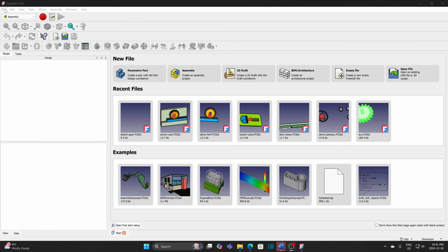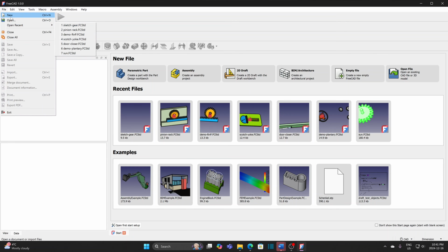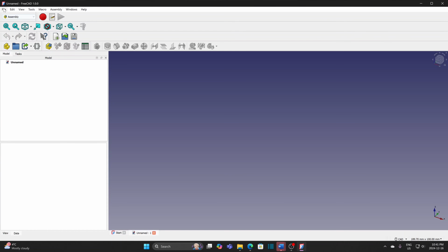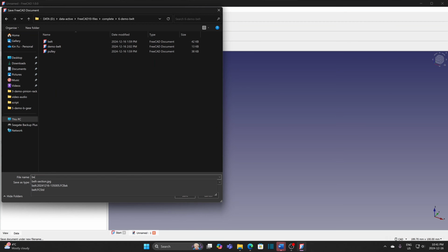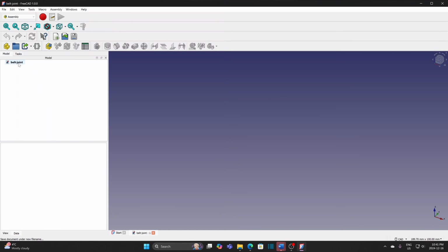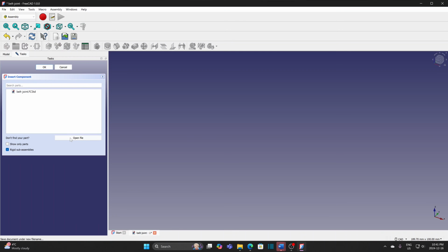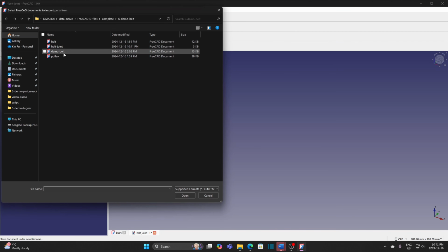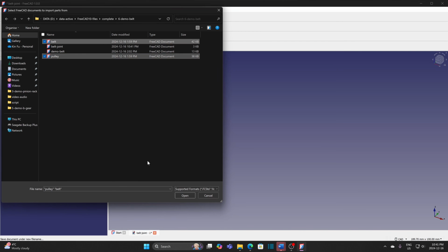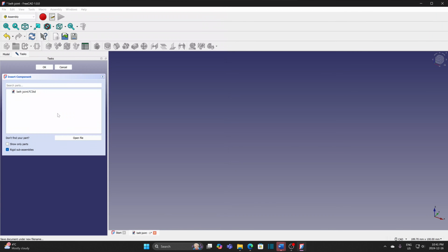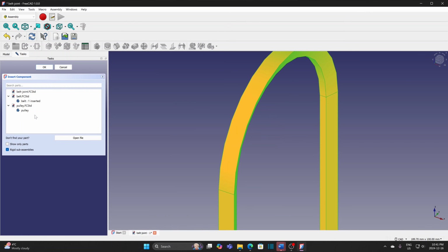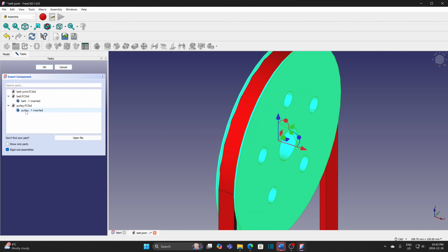Belt joint is to relate two revolute joints by the radius ratio, so basically it is the same operation as gear joint. Create a new file. Create assembly file. Insert components. Open files of components. Insert the belt first and ground this item. Insert the pulley twice, as I use two same pulleys for the example.